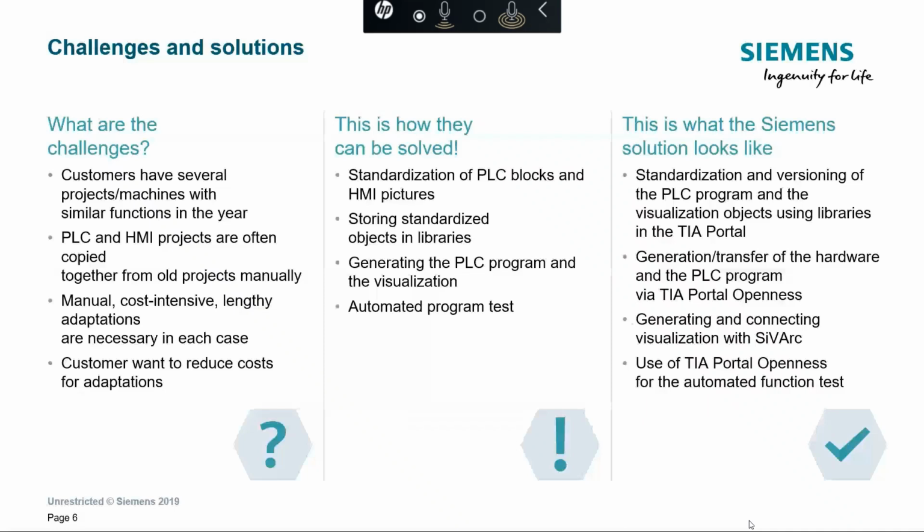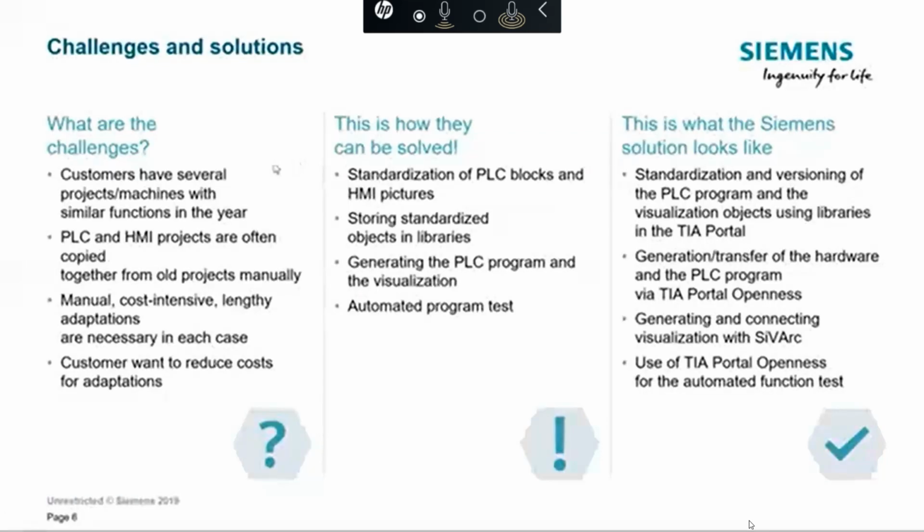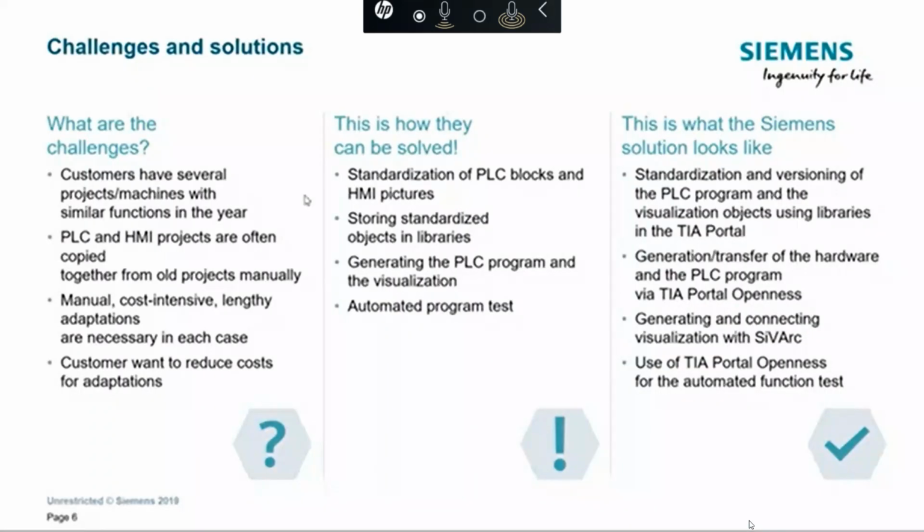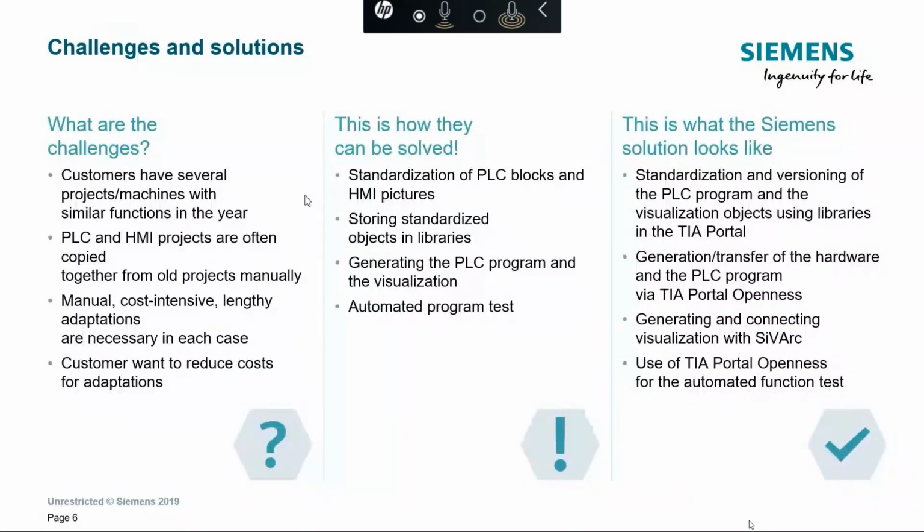Now, how could we solve this? Instead of opening that old project and copying the HMI faceplates or the PLC function blocks from the old system, if there were standard blocks and HMI screens developed, let's take the example of a pump control panel. If I am making some kind of automation system for controlling pumps, I assume that in the HMI screen you develop and in the logic you write, there will be some representation of the motors and the pumps.